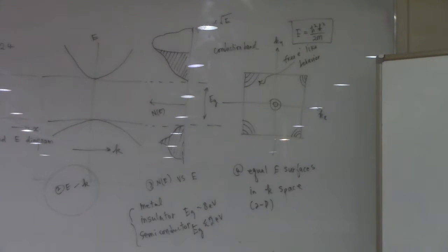Today we are going to discuss the application of these EK diagrams to find material properties like electron velocity, free electron velocity, which is related to the free electron mobilities as well, and effective mass, and some physical properties related to the EK diagram.